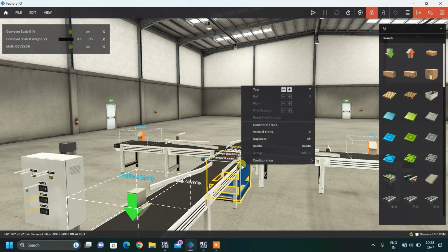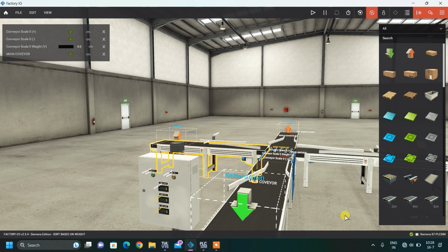Here you can see 10 volts means 20 kg. It means 1 volt means 2 kg. So 7.5 volts means 15 kg. In this way, I check the weight of all 3: small, medium and large boxes.